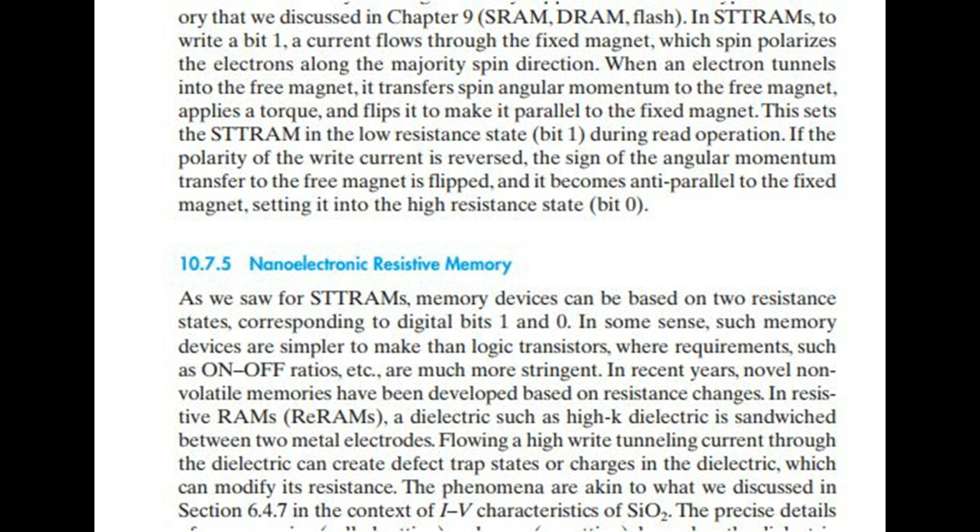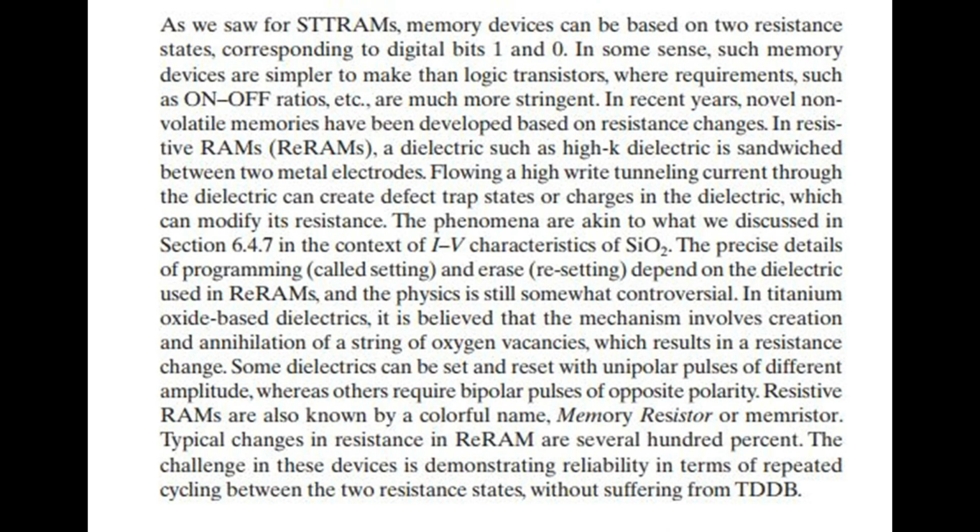The precise details of programming, called setting, and resetting, depend on the dielectric used in ReRAMs, and the physics is still somewhat controversial. In titanium oxide-based dielectrics, it is believed that the mechanism involves creation and annihilation of a string of oxygen vacancies, which results in a resistance change. Some dielectrics can be set and reset with unipolar pulses of different amplitude, whereas others require bipolar pulses of opposite polarity.